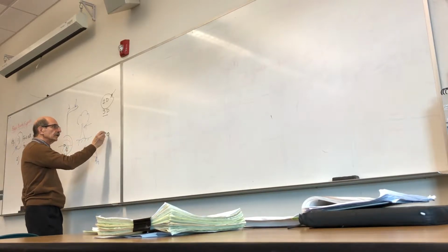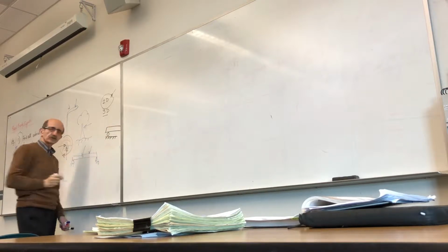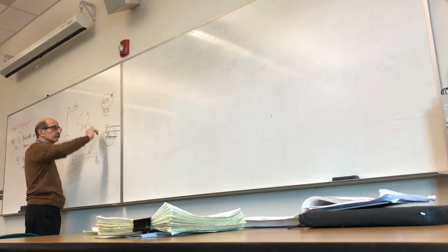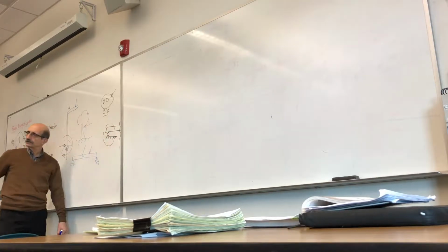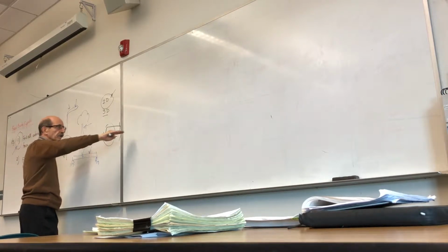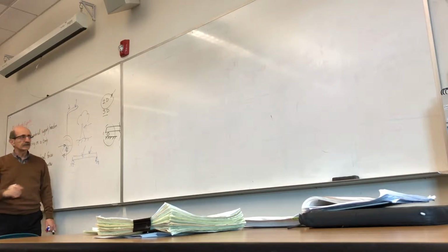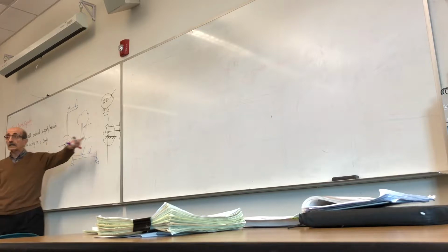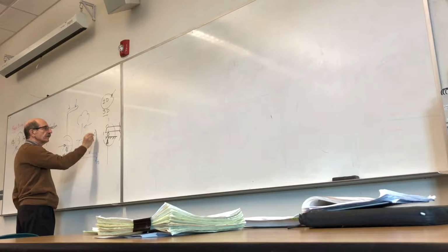That support maybe is holding the structure in such a way that rotation at the point of support is allowed. The structure, which is this one, is allowed to rotate. It is allowed to move, say, in this direction. Only the motion in one direction is not allowed, which is perpendicular to the allowed direction of motion in this case. We call this a roller.